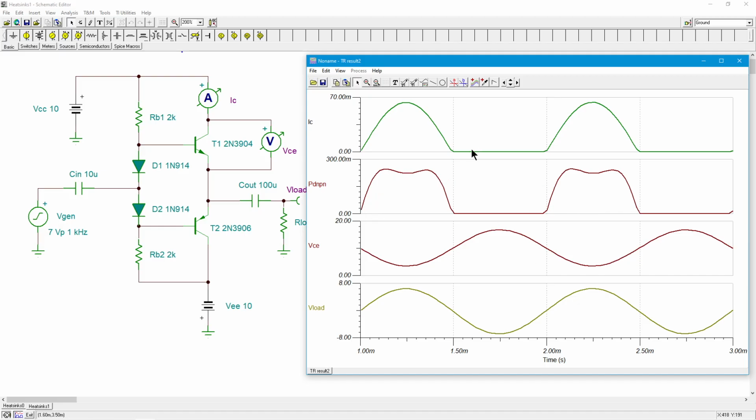Obviously, where the transistor has turned off, in other words, when the PNP is conducting, we have nothing for the NPN. So no current, doesn't matter what the voltage is. If there's no current, there's no power. On the other hand, when it is conducting in the push side of push-pull, then we have this half sine wave pulse coming in here, and the inverse of that for the VCE on a DC offset, basically. And we get this interesting kind of curve, all right?